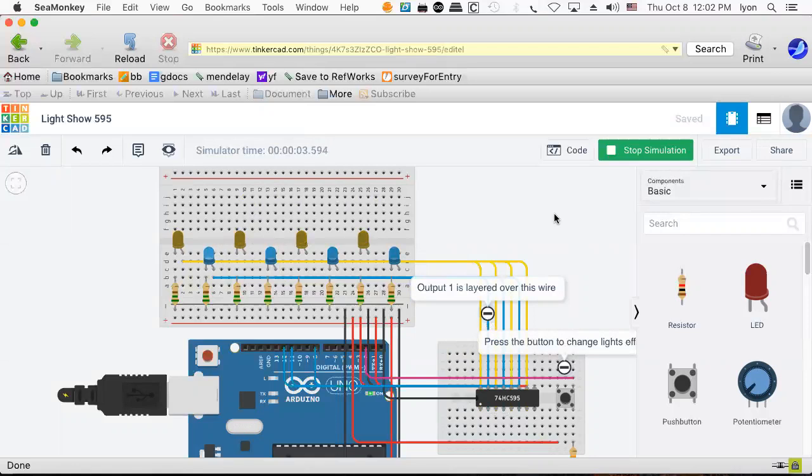And in fact, if you wanted to go so far as to have, let's say, a 16-bit DAC, you could have 2 of the 74HC595s chained together and get 16 wires on output, and then use that to drive your R2R DAC. And then you can have as many bits as you like for your DAC.